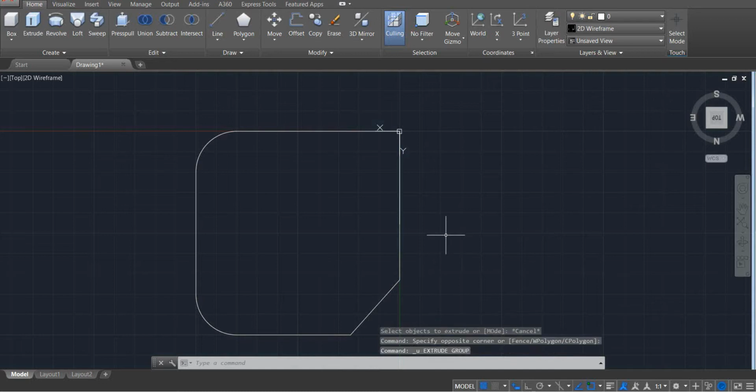That's why I was insisting all the time, if you use any line to assist you to locate a point, you have to remove it. Don't put two lines over each other. When you join the loop and you apply either revolve or loft or sweep or extrusion, these commands will not be applied because of this extra line.